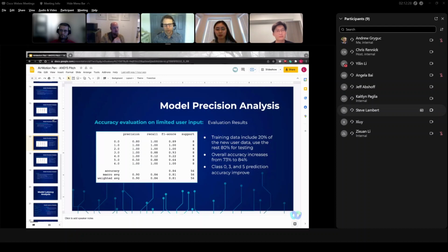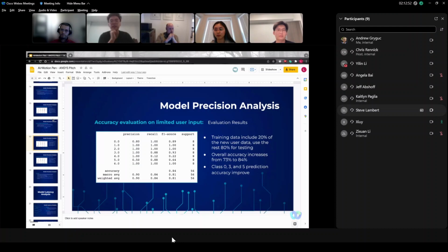Well, in terms of cursor control, our reference frame is fixed such that the z-axis, which is the top of the pen, should be pointing upwards. So in terms of the cursor control, yes, the pen position needs to be fixed. But in terms of the gesture recognition, our model can be user adaptive. So for different holding positions or different scenarios, as long as we give it, for example, 3 sets of data for each gesture, it will memorize the current scenario and the pattern of your input, and it will classify the correct gesture that you are inputting.